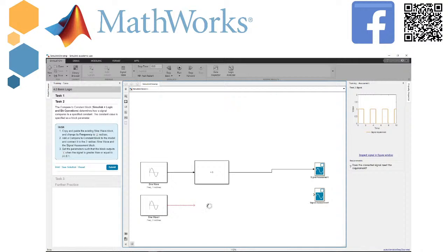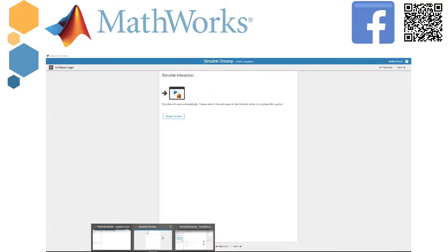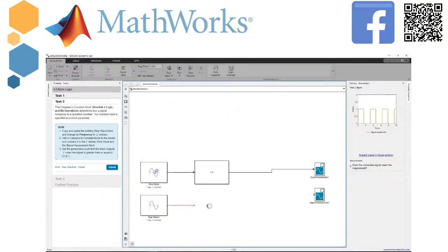Okay, so I will create our set. If speed is greater than 100, or the speed is greater than 35 kilometers per hour and lateral acceleration greater than 3 meters per second squared, we need to use mode 2. Otherwise, mode 1. Okay, so this is our pseudocode, and we want to implement it in Simulink.